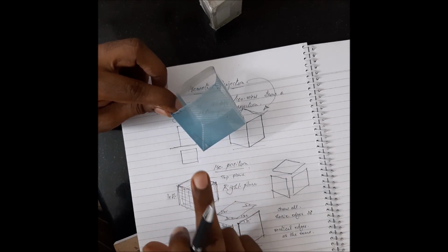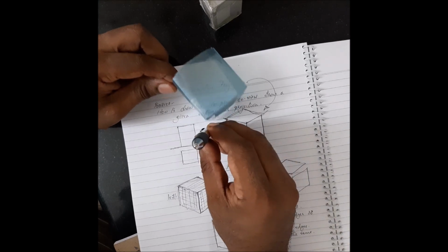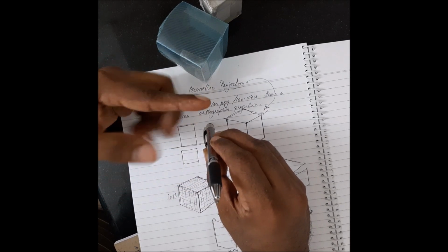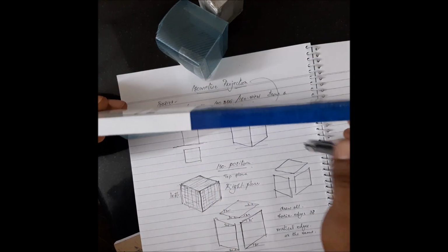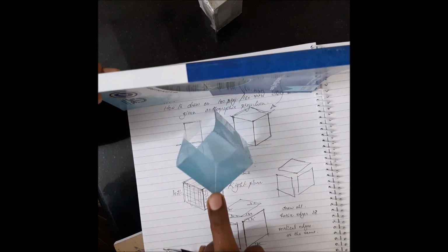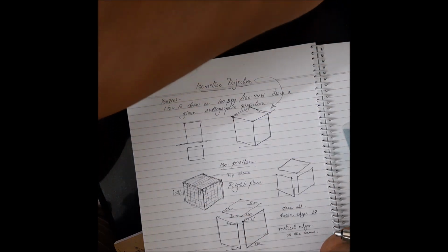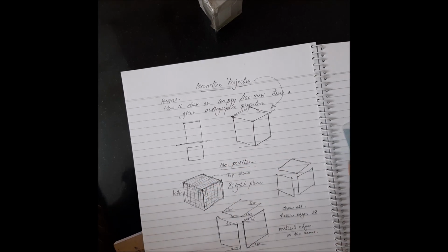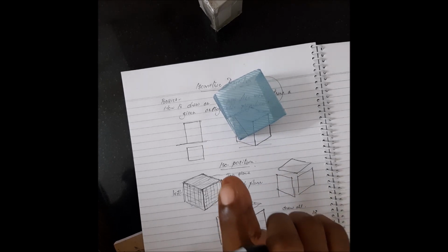As you can see, this is a case where the axis of the solid is inclined to both planes, which means, let's say the pen is your edge. When you keep it like this, it is inclined to HP and VP. Let's say this is your vertical plane and this is your horizontal plane. If you keep one edge, or all of the edges, inclined to both HP and VP, now if you know orthographic projection well, when any edge is inclined to both HP and VP, and you take the front view, you won't get the true length of that edge.